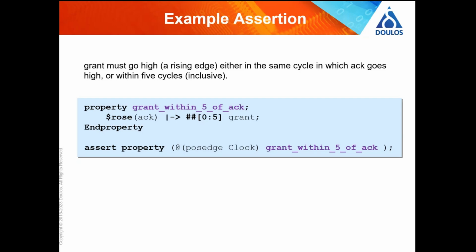And this second line of code here is what's called an assertion, and that is asserting that this property is true. So it's saying we'll do everything on the positive edge of the clock, and that name there must be true. And so you could simulate this, and if that is ever not true during any simulation, you'll get an error. Or you can run one of these formal tools and prove that it never doesn't happen. How cool is that? Really, really cool. Not a panacea. You'll find out why this afternoon if you come this afternoon.